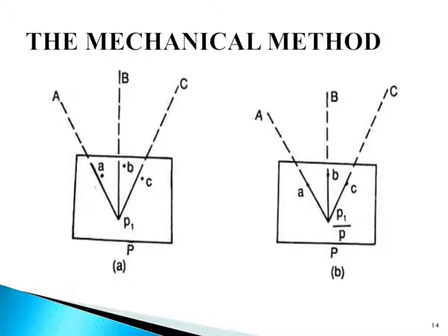Now the tracing paper is unfastened and moved over the map in such a way that the three rays simultaneously pass through the plotted positions small a, b and c. In this image you can see the tracing paper is set so that the rays pass through small a, small b and small c. Then the point P is pricked with a pin to give an impression of P on the map. This is the required point on the map, and the tracing paper is then removed.